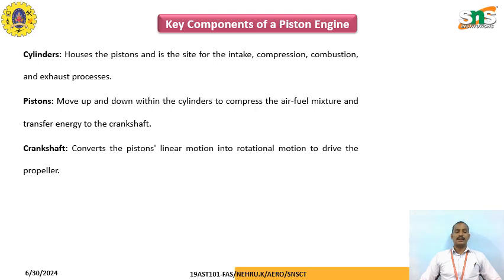Next, cylinder. The cylinder houses the piston and is the site for the intake, compression, combustion and exhaust processes. Piston moves up and down within the cylinder to compress the air-fuel mixture and transfer energy to the crankshaft. Crankshaft converts the piston's linear motion into rotary motion for the propeller.